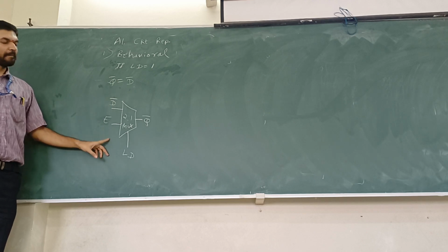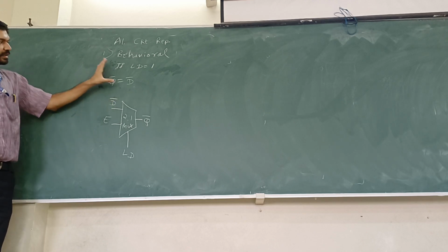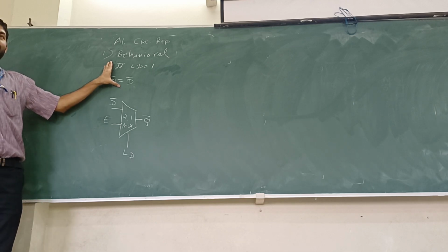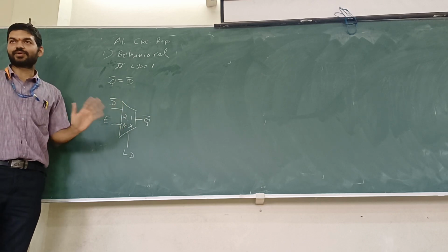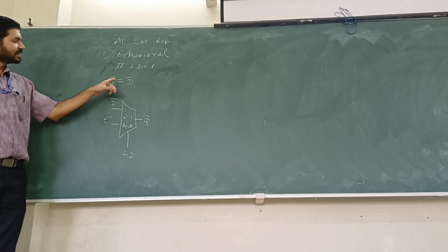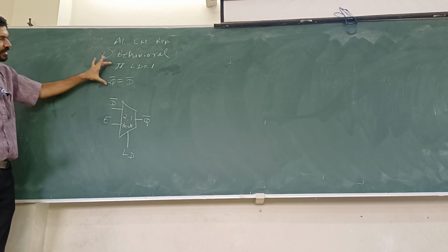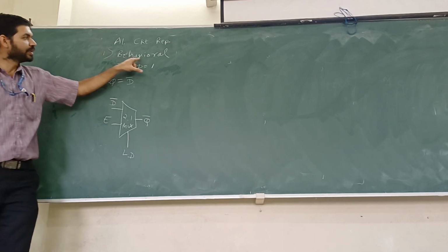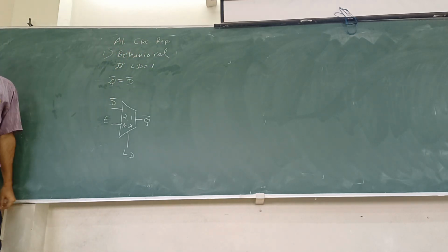Code. So this is not clear. It is just telling the behavior of the circuit, whether it is the flip-flop or particularly a mux or any other thing. We don't know. But how the circuit behaves is all we are representing. This style of representation is called the behavioral style of representing the circuit.